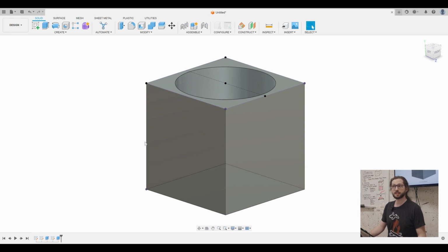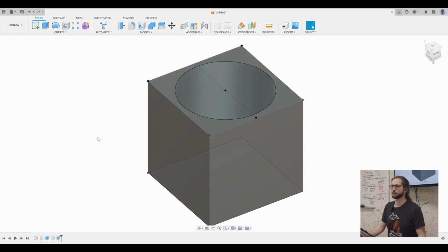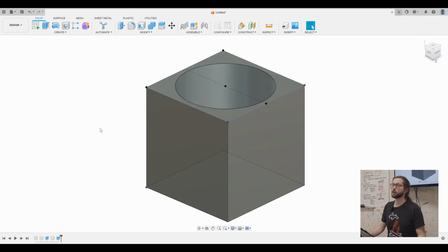So that was that offset. So I could take the offset. Yep. You can do it twice, so you could do it one way and then offset it. You can always use a sketch and the transform tools as many times as you want.